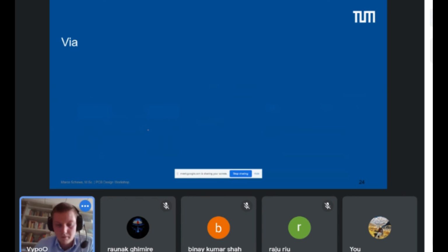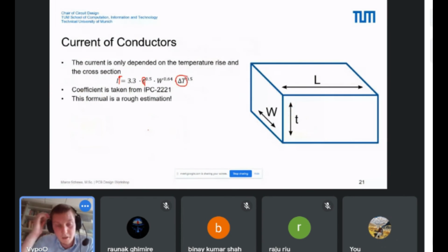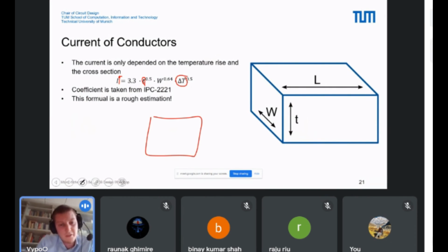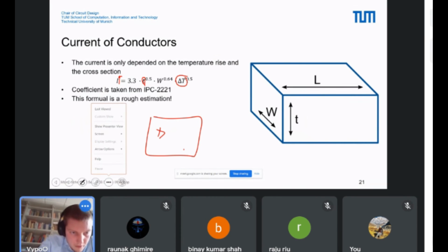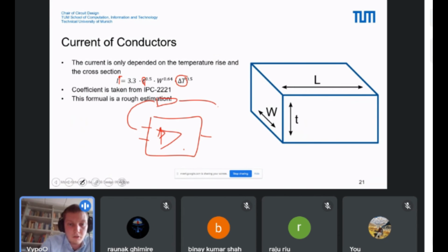And if you buy an op amp IC, then it can give you advice to buy one with 2 op amps inside. Because if you have only one op amp inside, then you have the output on the right side and 2 inputs on the left side. It means if you have a feedback, you need long traces.